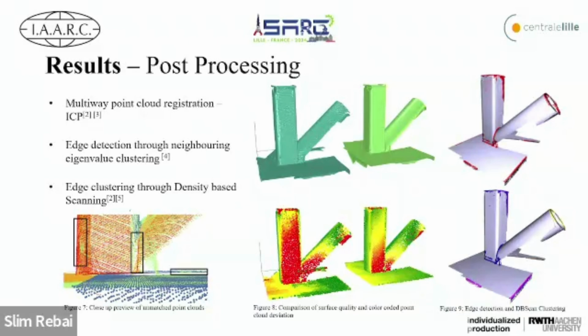The next part would be the previous video, but I think I can't play it, but it would show how the scanning procedure works. The robot has the line scanner and a welder attached to it. First, an approximate position of the joint is given. It has been scanned, and after the scanning, the edges are extracted relative to the robot base. Then after the tool change, the physical welding tool will be on the robot. It will go there, weld it, and retract back. Then there's also one more pass for quality inspection.